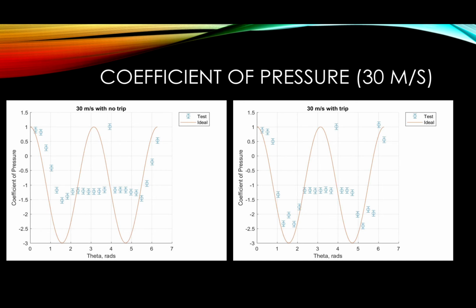We compared our graphs to the lab manual profiles and saw that for both tests, the flow over the smooth cylinder was very laminar, as seen by the graphs on the left of both of the slides. Also, the trip strip did its job and added a lot of turbulence, which is shown in the right graphs.